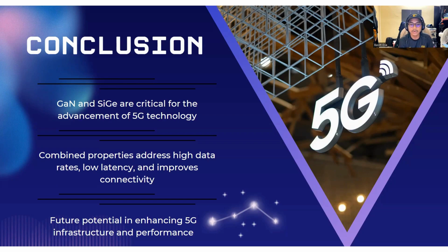The tunable electronic properties of silicon germanium are due to its variable silicon to germanium ratio, and it allows performance level for high frequency and mixed signal application to be optimized. This property is of considerable importance since 5G will have many needs, such as radio frequency components, and more complex signal processing units in a single integrated circuit.